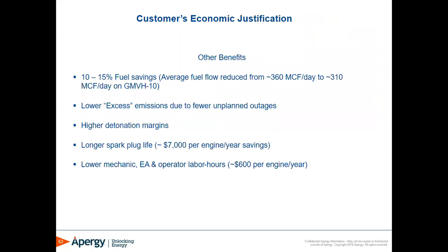Some other benefits they got from this system: 10 to 15% fuel savings, lower excess emissions due to fewer unplanned outages, higher detonation margins. The higher detonation margins refers to detonation within the power cylinders that results from changes in their BTU content. Longer spark plug life, lower mechanic, EA, and operator labor hours.